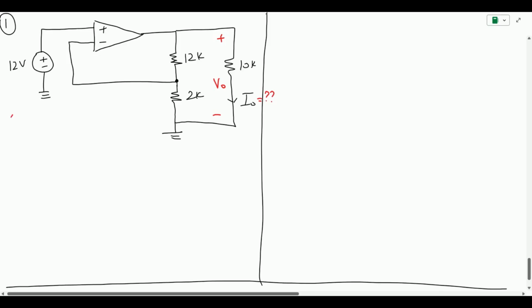In order to solve this interesting question, we are not given any biasing voltages. So again we are not interested in finding the negative VCC and positive VCC. It is only given when we need to verify whether the operation is in the linear region or the saturation region. So in order to find this, assign the respective voltages. This will be Vp, this is going to be Vn, and this is the Vout that we have given. We know that the currents entering will be In and Ip.